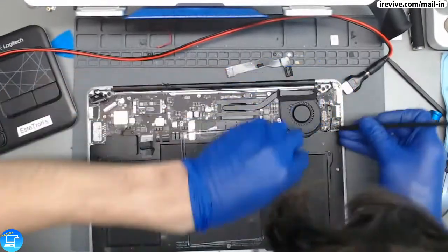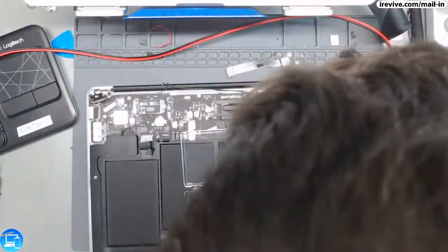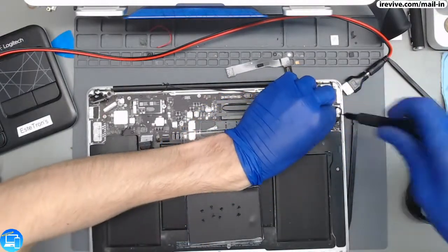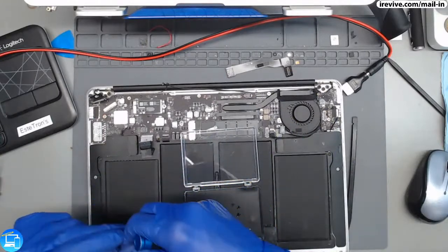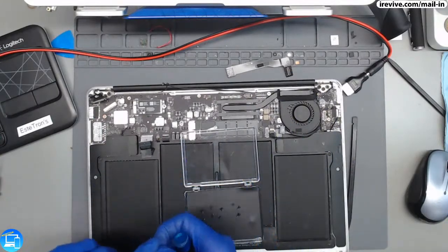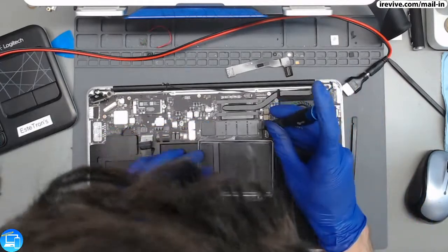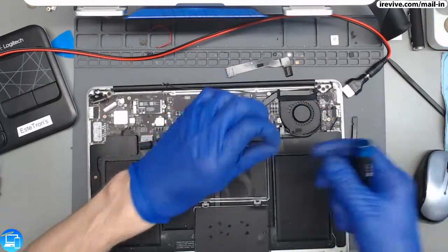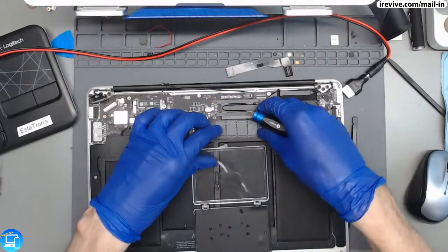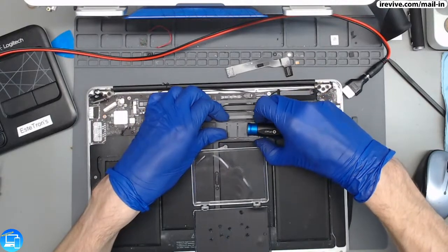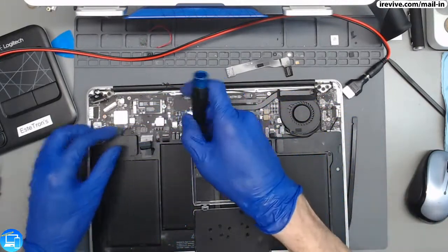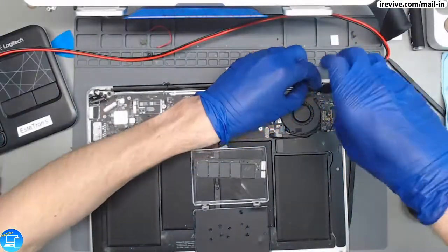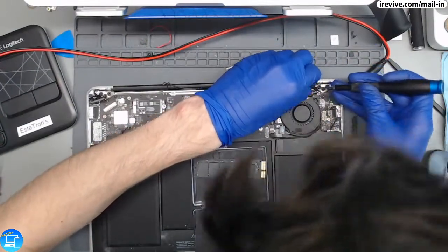Are you being a bipolar computer? You want to work sometimes and other times you don't? I've got an A1708 at 5 volts and 3 milliamps, worn out USB-C ports. Anything at 30 milliamps. Is it 30 or 300 milliamps? Because it sounds to me that maybe just the USB-C port is, like you said, worn out.